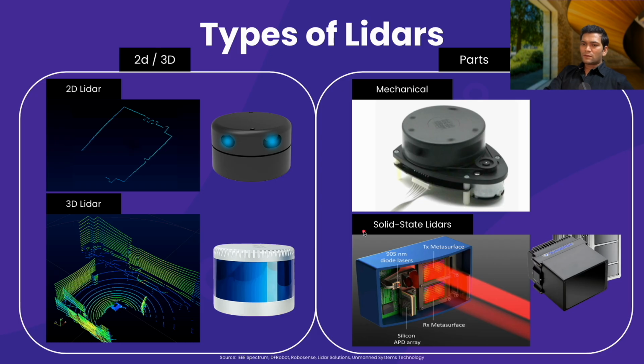Most commonly, the way they capture the world in 3D data is by flashing a 2D array of light pattern. Just think of a flashlight, right? And how it will illuminate a section of the environment when you turn on the flashlight. Except this flashlight is now an infrared flashlight, and each of the beams that is sent through this flashlight is read back by the lidar. So it kind of creates a distance array of the signal.